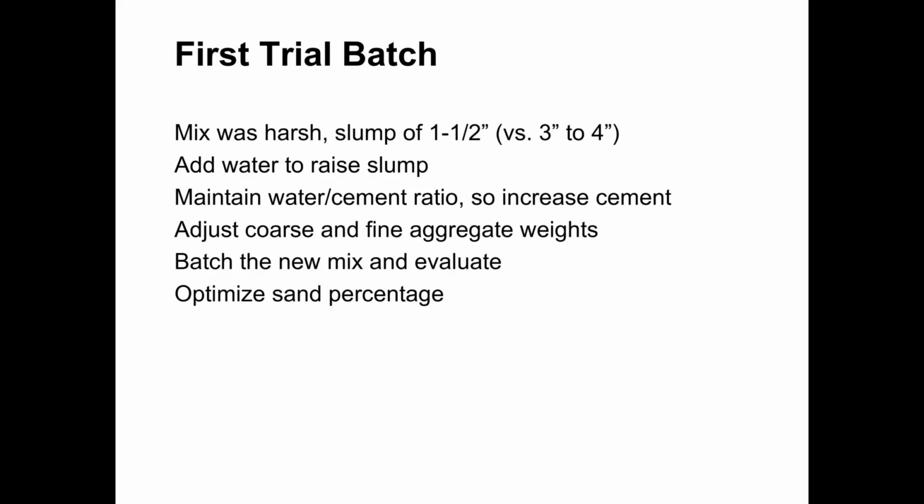Once we've gone through this process, we would then batch a new trial batch and evaluate whether these adjustments that we've made are helping the mix to be closer to what we would anticipate and what we need that mix to be. So generally, we're going to go through the trial batching process more than one time. We're going to keep making small refinements to our mix design with each trial batching session until we have that mix dialed in so that it is performing the way that we need it to perform.